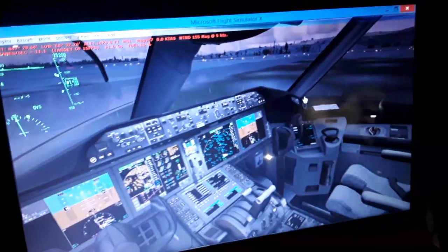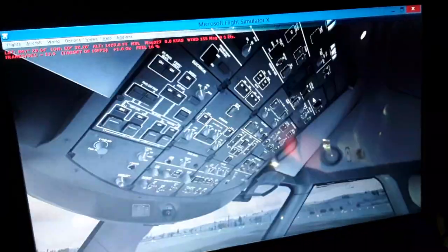Also the aircraft is gonna fly with an airspeed 2 or 3 times faster than at sea level, so it's gonna have a higher intake of air from the front fan stage inside the engine for burning and for compression. So we're gonna have a different fuel mixture every second as we fly from takeoff, climb, cruise, descent, approach, and landing, and vice versa as we descend. The FADEC controls the fuel mixture every second automatically instead of doing it manually like in the smaller turboprop and piston aircraft. So it's a good thing to have the FADEC installed in your aircraft.